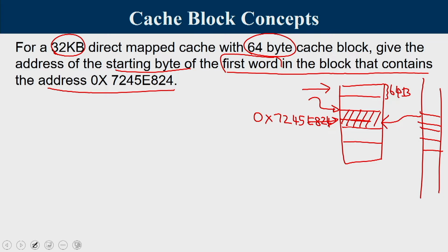We have to understand that when you bring contents from the main memory, you are bringing a block of data, and these are continuous blocks inside the main memory. So, if you look at the addresses of those words that are brought into one cache block, they will differ only in a few least significant bits, whereas the most significant bits of the address will be the same. When you move to the adjacent byte inside main memory, there is a change only in the LSBs. Keeping this in mind, let us understand the context given in this question.